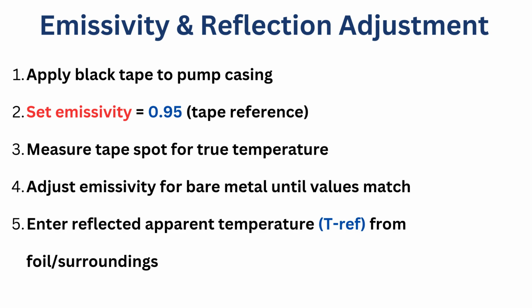And since we have already discussed in the last video how you can adjust the emissivity, and how you can check what emissivity value is suitable for a particular asset, we will still repeat it here again. So let's say you want to measure what emissivity will be best to monitor the pump casing, which has a shiny stainless steel surface.